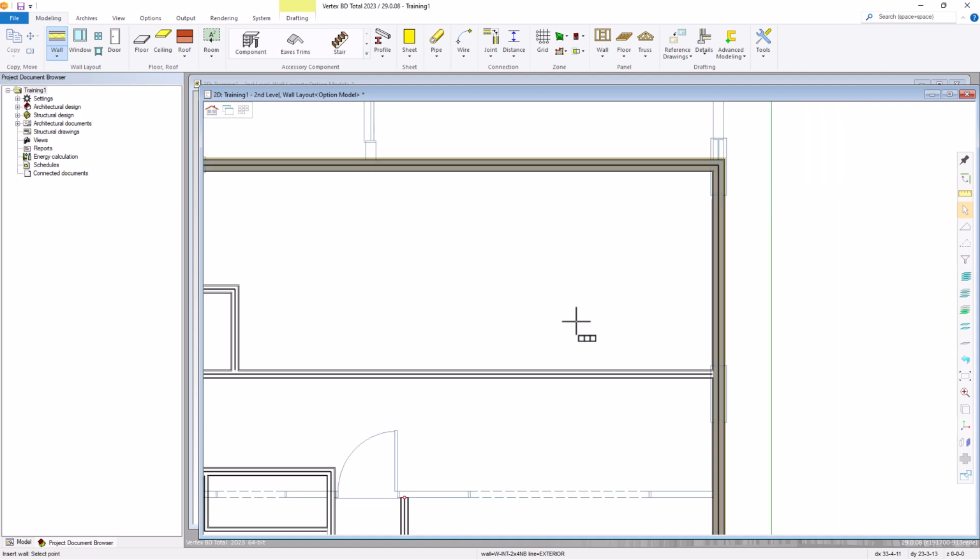Let's zoom in. Let's add a few more walls. Select the location along the back exterior wall. Run the wall vertical, select the I key for the Y axis, and extend the wall down to the horizontal wall. And V key to confirm. We have another closet wall around here, so we'll just click anywhere there. Hit the letter I for the Y axis. Bring that down and butt up against that wall.